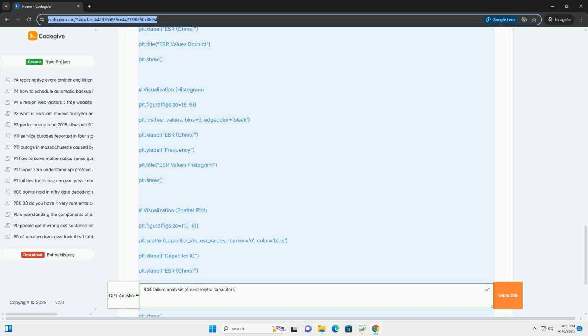Voltage rating: use replacement capacitors with a voltage rating that is equal to or greater than the original capacitors. It is generally a good idea to use a higher voltage rating for improved reliability. Low ESR capacitors: when replacing electrolytic capacitors, especially in power supplies or other critical circuits, use low ESR capacitors designed for switching power supplies or automotive applications. These capacitors offer improved performance and reliability.